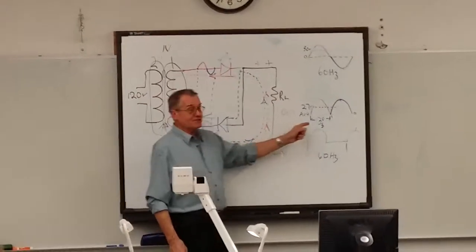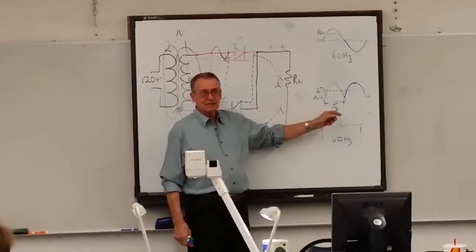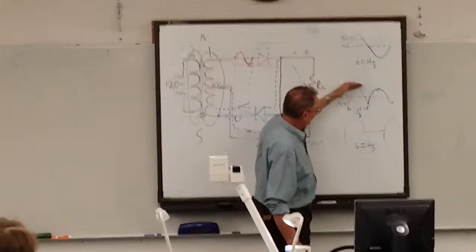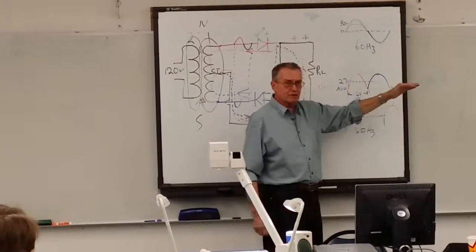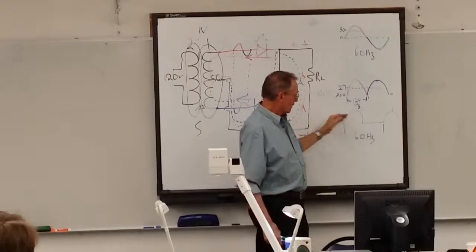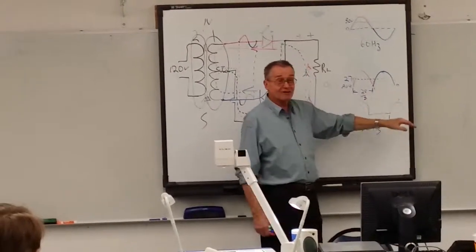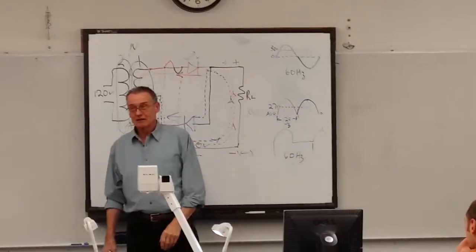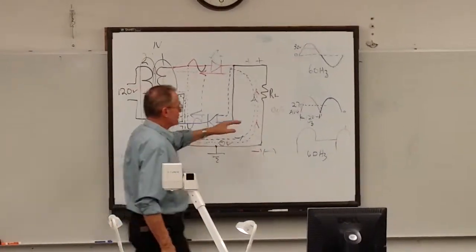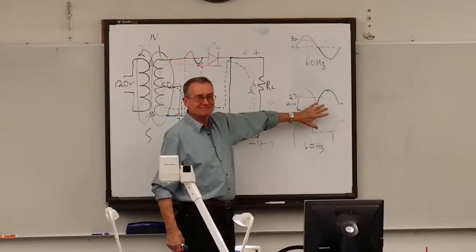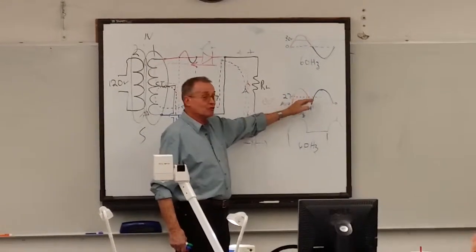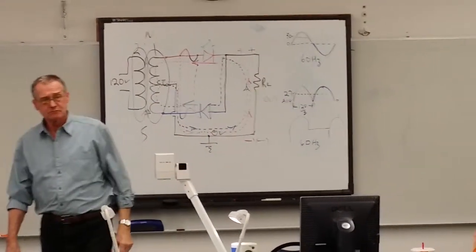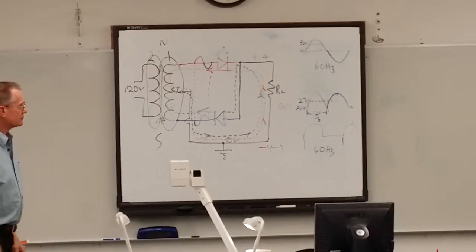what happens, this is easier to filter. It's like if you were driving a car pretty fast and you hit here and there, and you have to catch those, you'd be at the same level, you wouldn't feel a whole lot of bump, would you? But what if you had to jump from here all the way to there? You'd have to travel twice the distance to get to that other peak. So this is called smoothing the output. We make it a little bit smoother, it's not as rough as that would be. And to a capacitor, that's important. And you'll see later why that is.